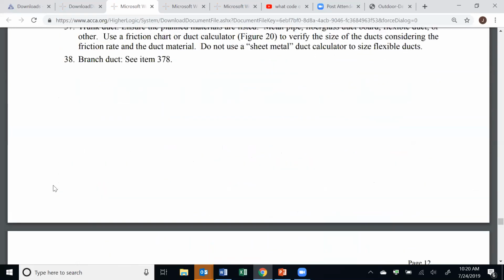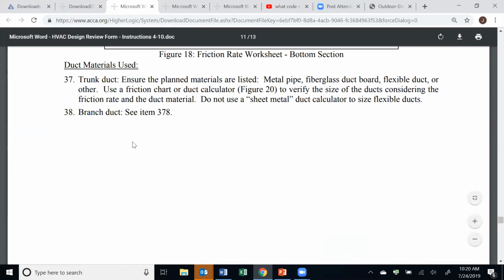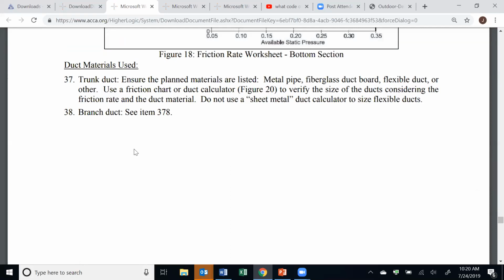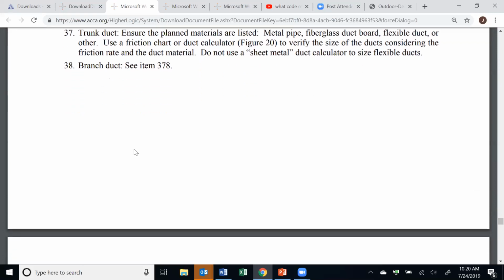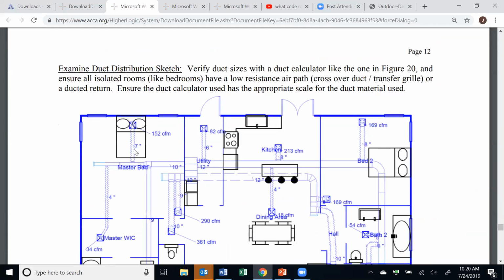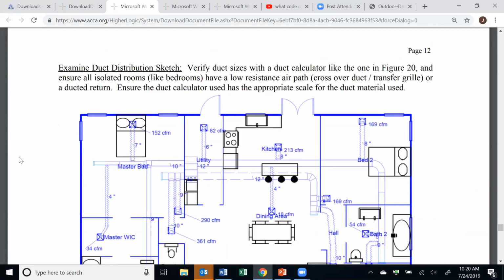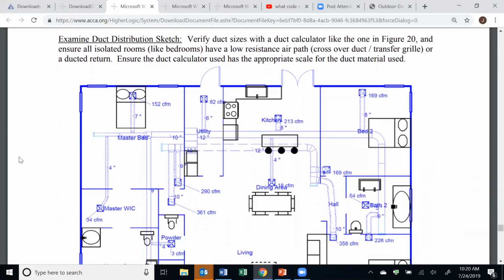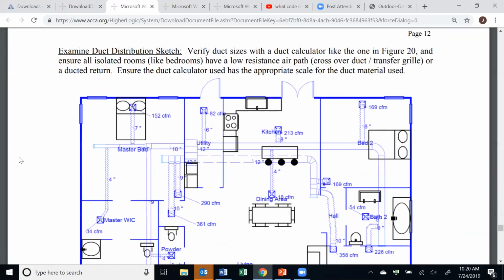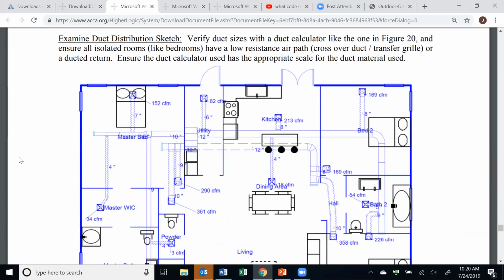Okay, that's what I know. The city of El Paso, for example, does require a duct board trunk, and they're only allowed 10-foot maximum flex duct branches unless it's stamped by an engineer. You get a whole lot more certainty in the effective length on a trunk and branch versus 95% of the contractors. Again, it's an undersized duct board plenum, and for all intents and purposes, it's flex duct trunk and branch. Yep.